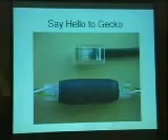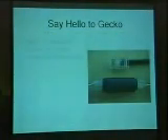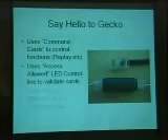So this is Gecko. It's really small, it's really cheap, and it uses command cards. Basically, it has its own little set of cards that it knows to look out for. It's its own tiny access control system. It uses the access allowed LED, this one doesn't, but the V2 one does, to say, oh, I've just seen a Wiegand ID go past, and the access allowed LED went on, so it's a good card.